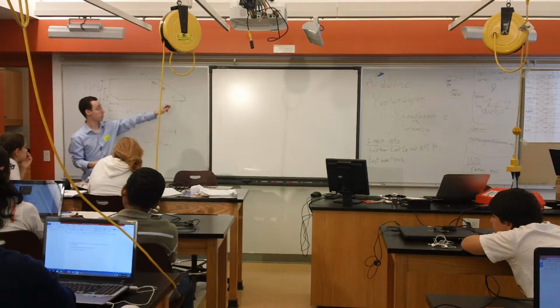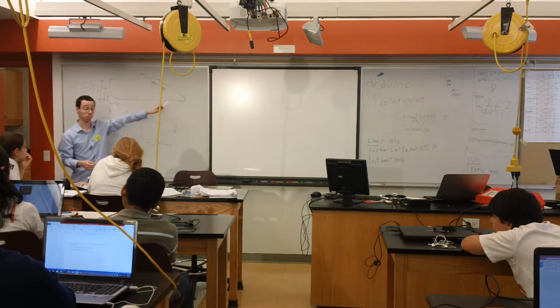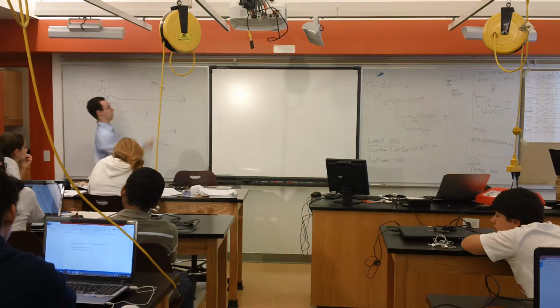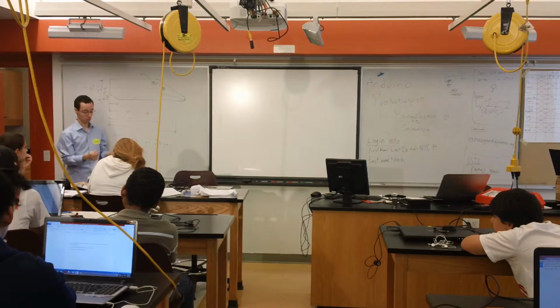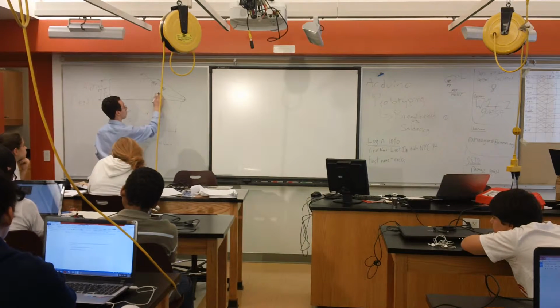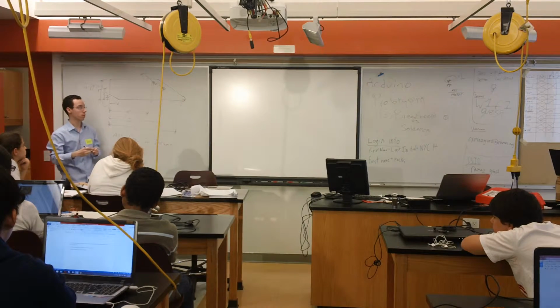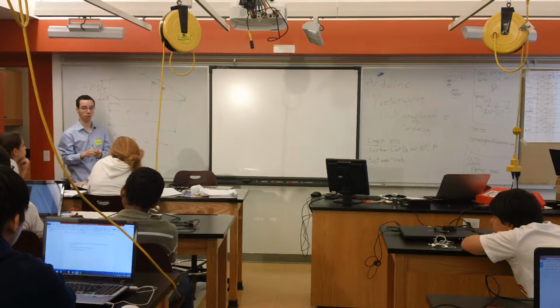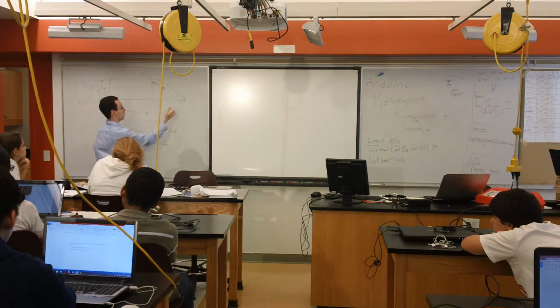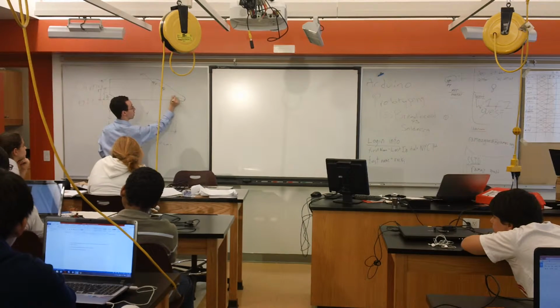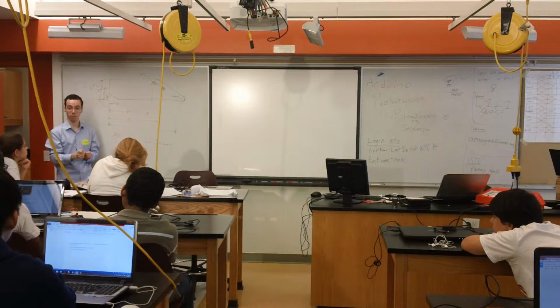If I'm specifying something rounded like this, it's not a complete circle, so giving a diameter for this wouldn't make any sense because there's no diameter, it never ends. So instead what we do is we specify a radius, because in our case, this is a part of a circle. It gets weird when you're dimensioning parabolas and other weird curved shapes, but we won't talk about that. So here, instead of giving a diameter, I would give a radius. So I would go radius 0.5 inches in this example.